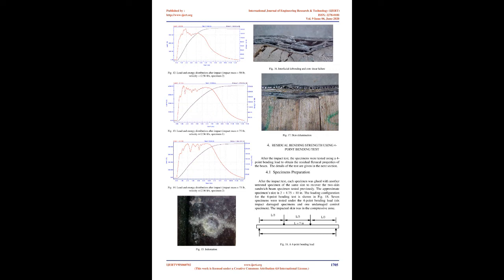An environmental conditioning chamber is integrated with the equipment. The temperature range is controlled with an electronic thermostatic controller from minus 58° F to plus 347° F. The clamping fixture, which simulates a rigid clamping with a force of 160 pounds, is located within this environmental chamber, ensuring that specimens are tested at the desired temperature. Communication and data acquisition with the impact test machine is via a computer-integrated control and data acquisition system.